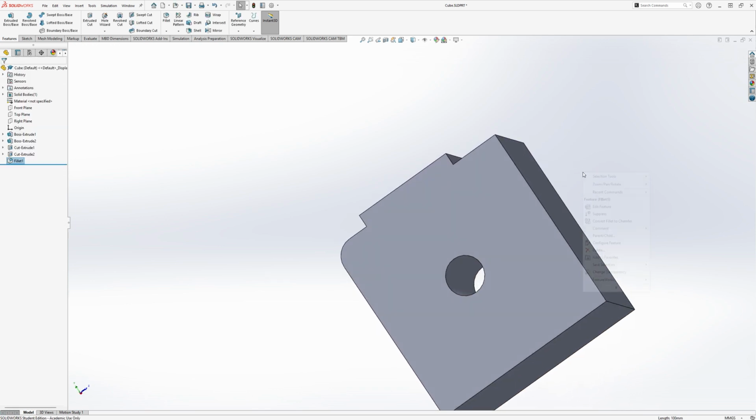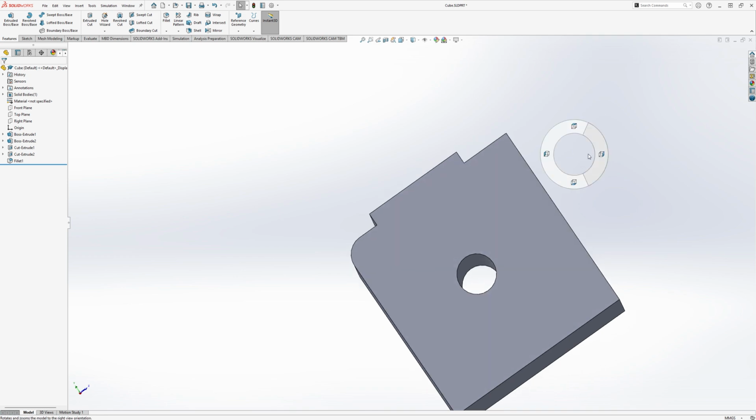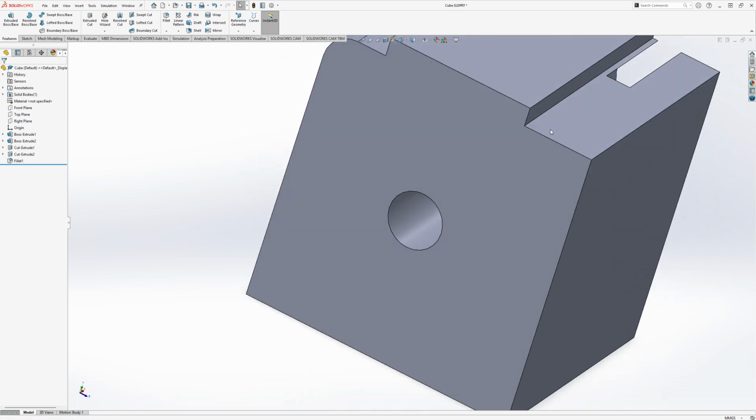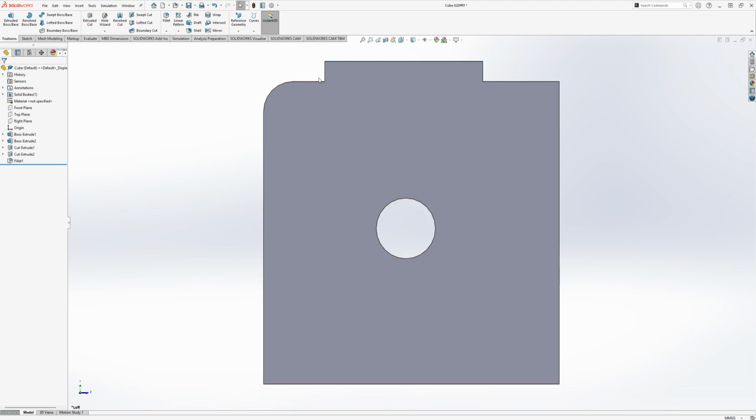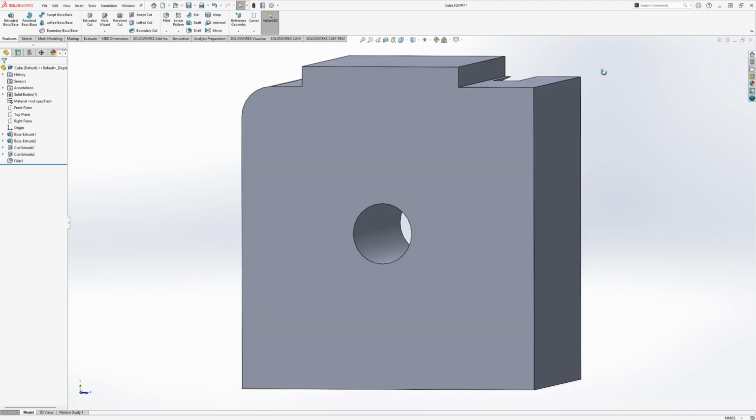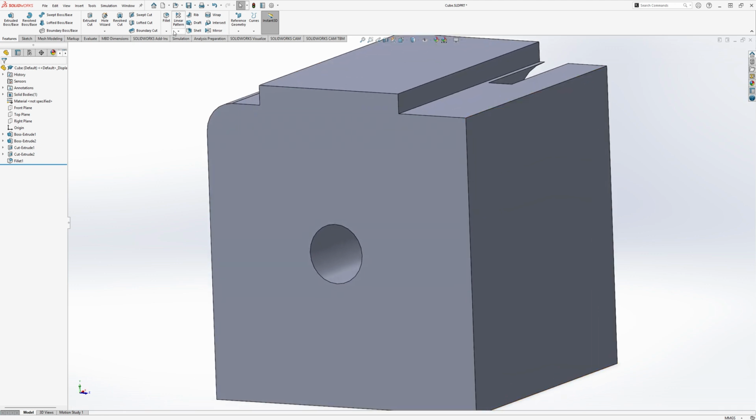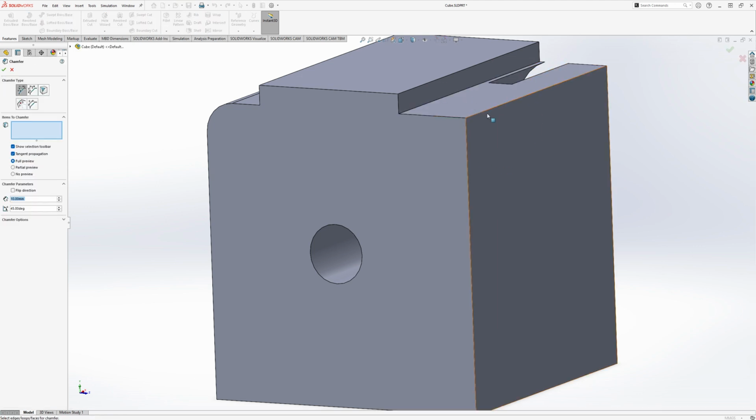You can see the differences. Actually, let's go to this edge. You can see the difference between this side and that side. This one's 90 degrees. This has a radius. With this edge, let's add a chamfer. We're going to go to the fillet section here, go down, go to chamfer.